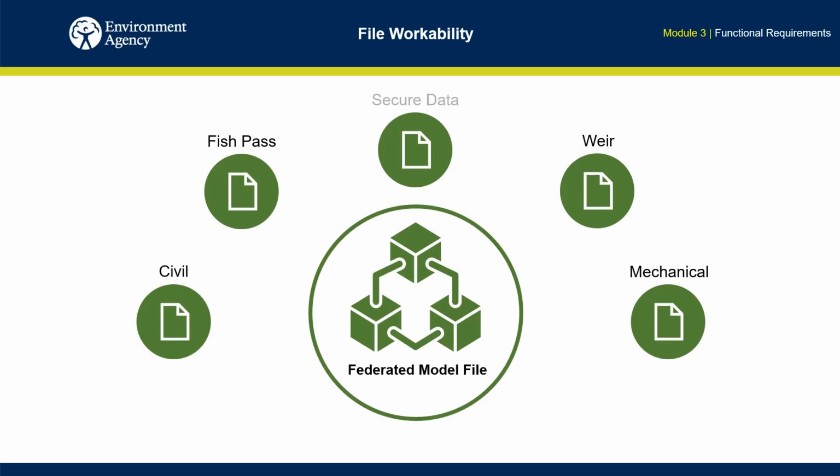Models may also be created to segregate secure or classified data so that it can be controlled in the right way. These separate files are brought together in the federated model file, where each can be reviewed against one another and the design process coordinated from a single source. Keeping model memory sizes to a minimum is important, as this avoids slow speeds when viewing or amending the files. A guide to file size limits is provided in the Environment Agency's Employer's Information Requirements.